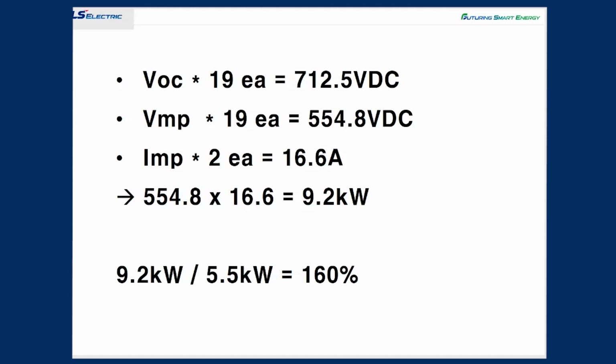Then that rang the bell about the winter. How about winter when it is cold? Well, I can answer for that. I think the VOC voltage may increase in the winter time due to the low temperature. So, the appropriate number of panels in series should be considered.